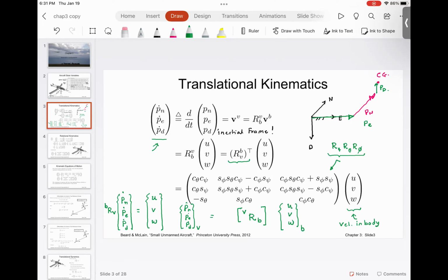So what I need to do is get these accelerations in the body frame, integrate those, and then transform those positions back into the inertial frame. So that is what is happening over here. This rotation matrix will take the accelerations or velocities or integrated accelerations in the body frame, use the rotation matrix and transfer it back.